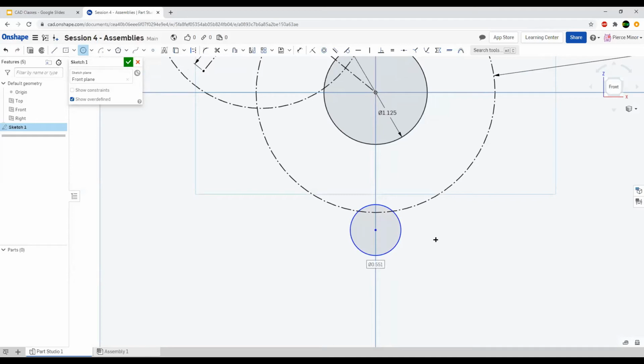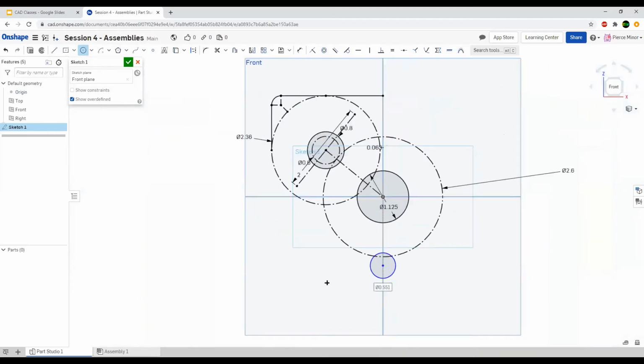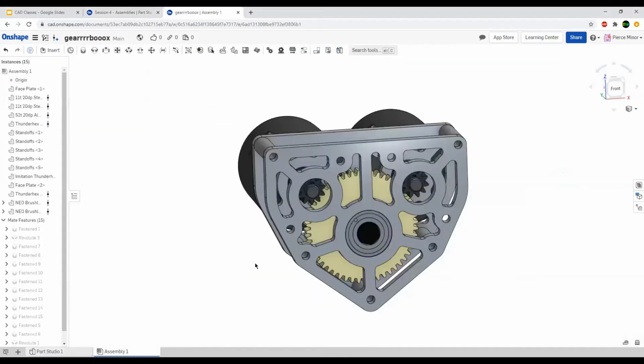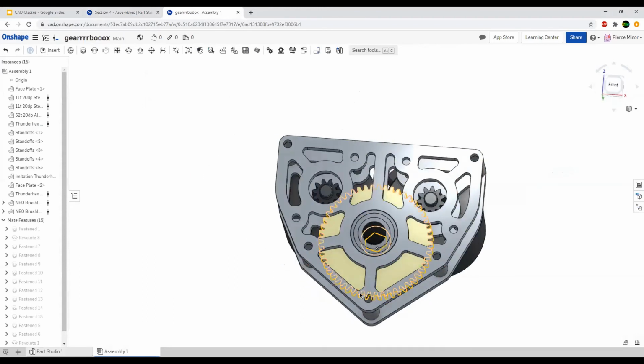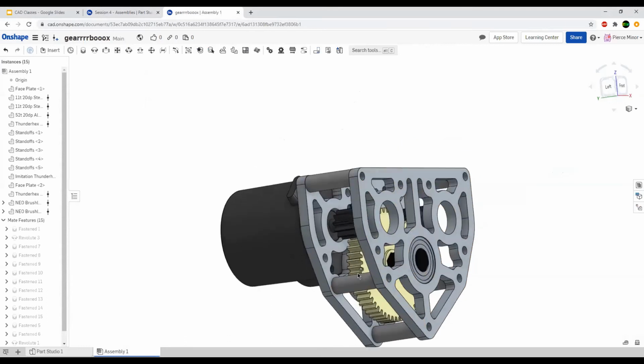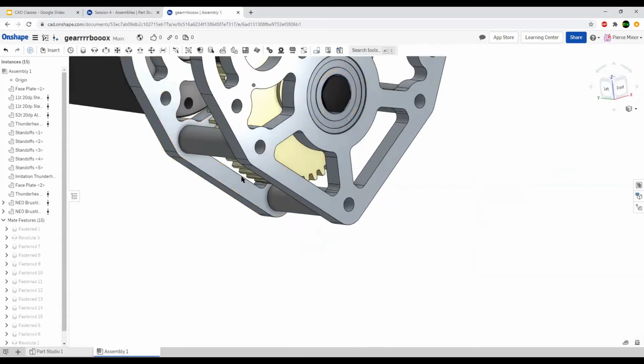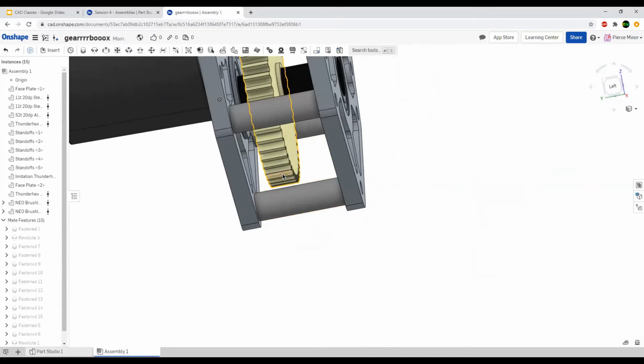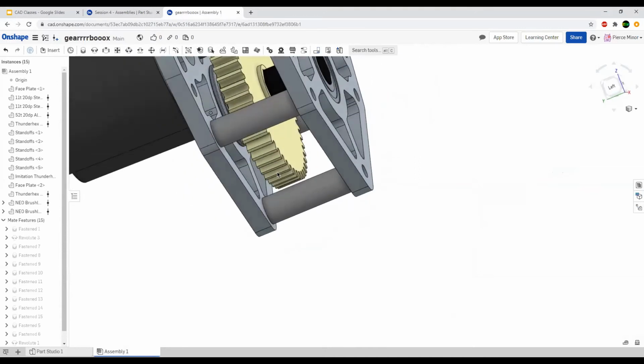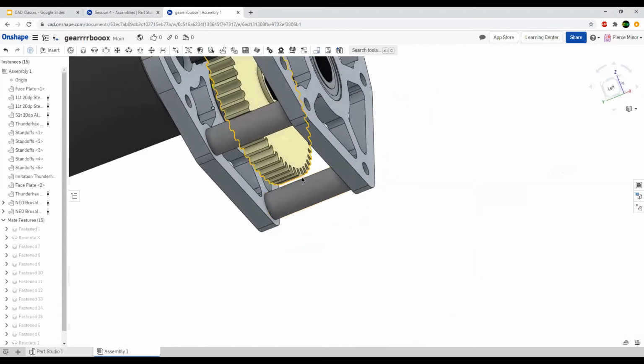I want to have another hole at the bottom that I use for a standoff, because of the way I'm going to have this set up. In fact, I'll bring over the assembly I was working on last night. So I have a hole at the bottom for this standoff, one for this standoff, and one for that standoff. I need to make sure these standoffs are not going to be hit by this gear when it's in motion. As it is, this is actually really close. I made a bit of a mistake while making this, and that's definitely too close. I'll have to change that a bit.